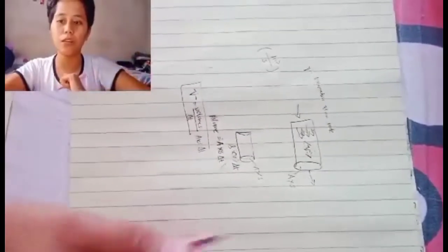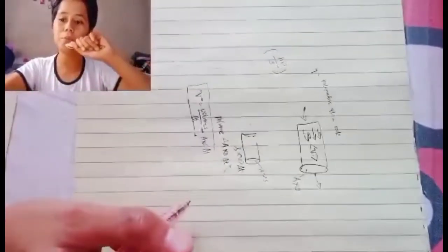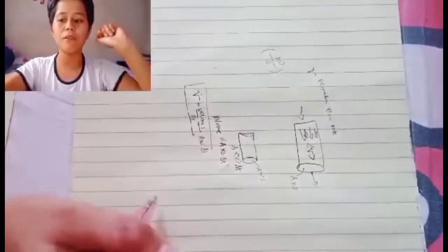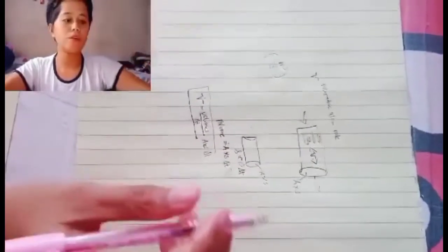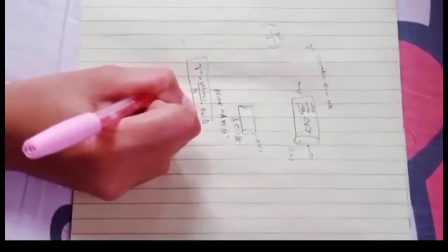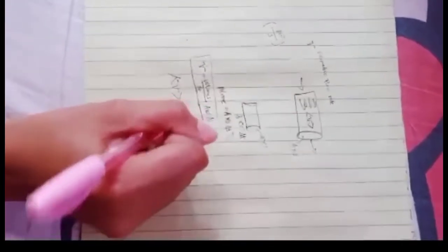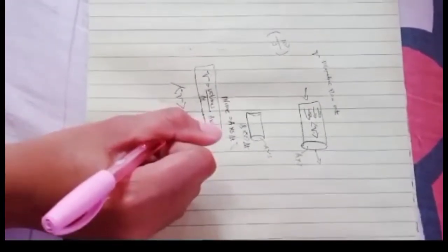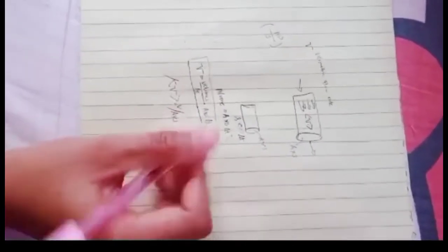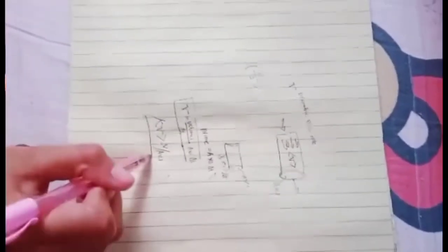We can always calculate, for steady turbulent flow, the volumetric flow rate from the cross-sectional area times the average velocity, or conversely, we could calculate the average velocity as this volumetric flow rate divided by the cross-sectional area.